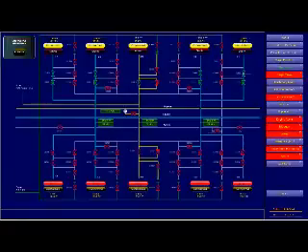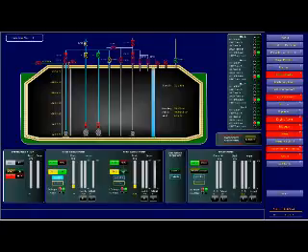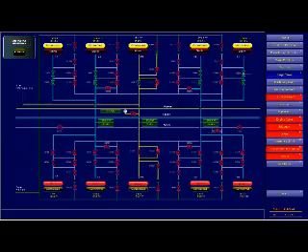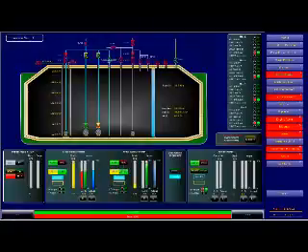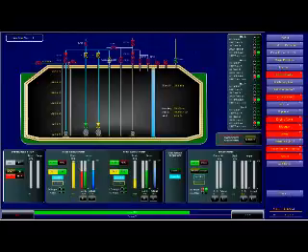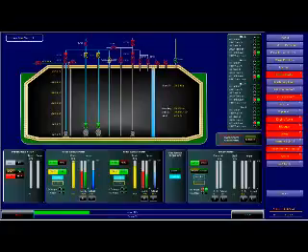Maximum, how much should the temperature go down? Minus 180? No, not necessary. We'll never go down. Whatever is the cargo temperature, we'll get, because we are not running any refrigeration at the moment. We can't expect anything like that. Our cargo is minus 160.2 roughly. The lowest, it was loaded at 161. It has gained some heat altogether. So is it running now? All 4 tanks? No. Okay, take your time.